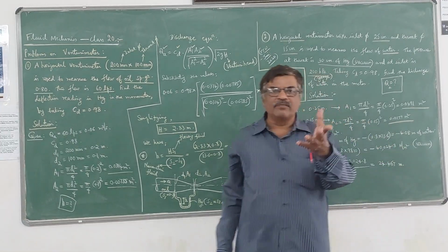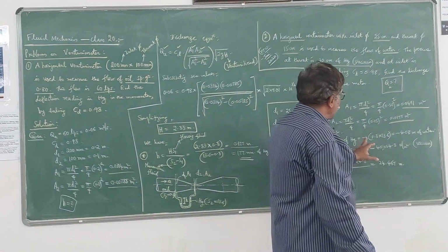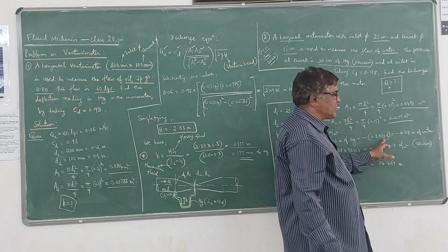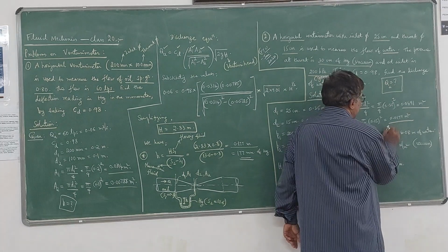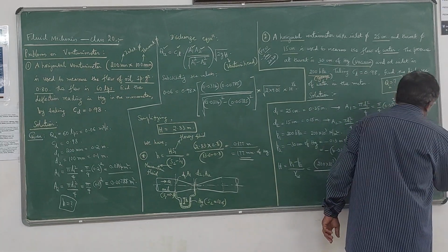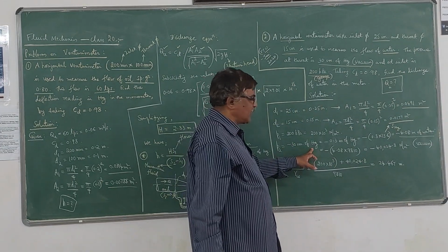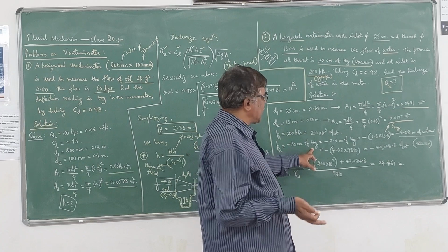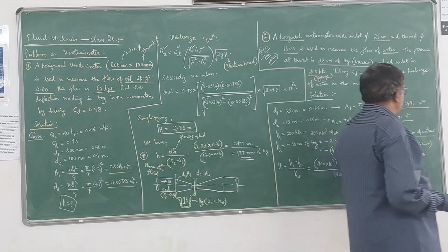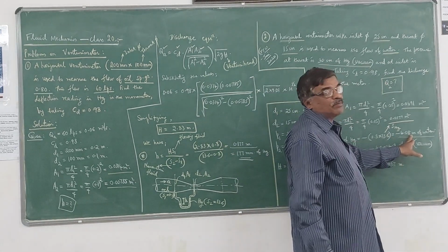This I have explained in the fluid pressure chapter, so you can refer to that. So minus 0.3 into 13.6, the specific gravity of mercury, you will get minus 4.08 meters of water. That means minus 30 centimeters of mercury is the same pressure as minus 4.08 meters of water. Now once again this should be converted into Newton per meter square.